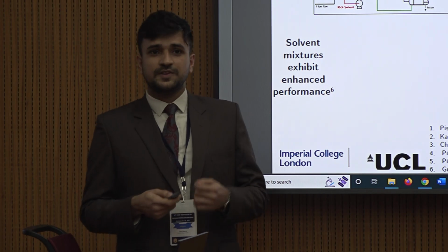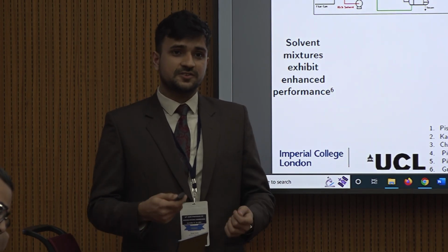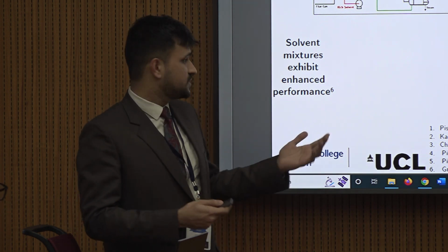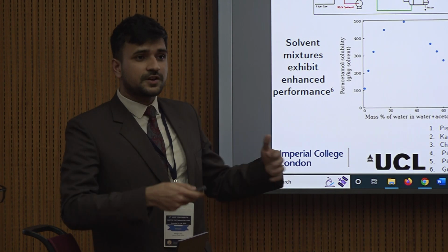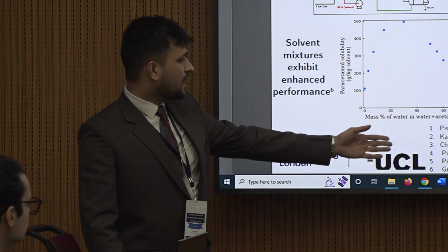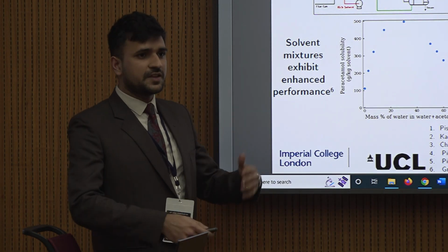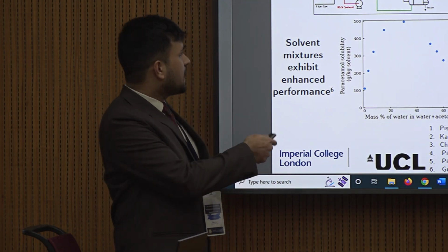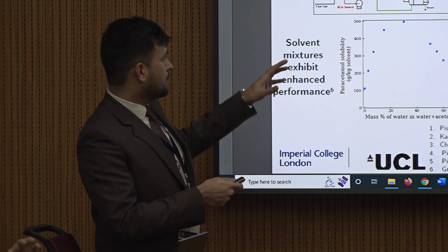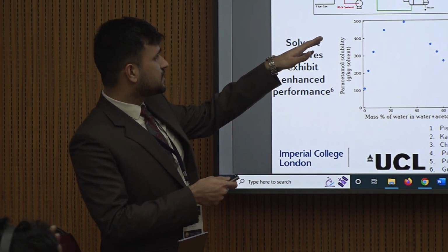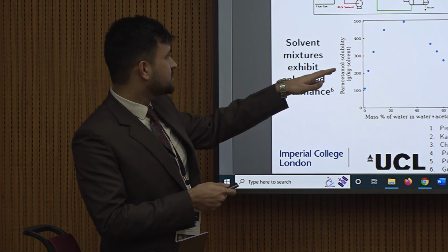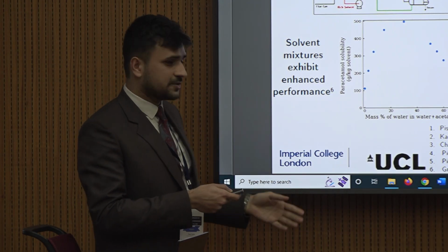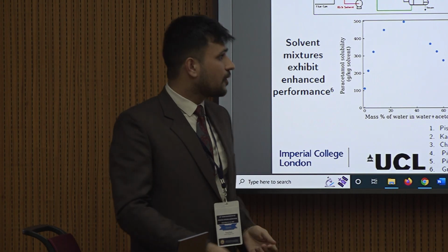Also, in many cases, we found that mixtures of solvents actually perform better than pure solvents, and I would like to show that using an example. If we consider a very common drug, paracetamol, Granberg and Rasmussen conducted experiments on solubility of paracetamol in a water acetone solvent mixture, and as you can see from this plot, solubility in a 30-70% water acetone mixture is at least 5 times higher than either pure acetone or pure water. So there's potential for enhanced performance.